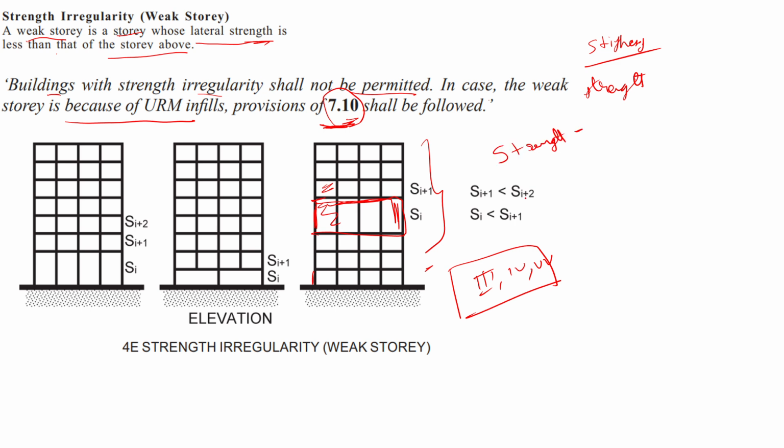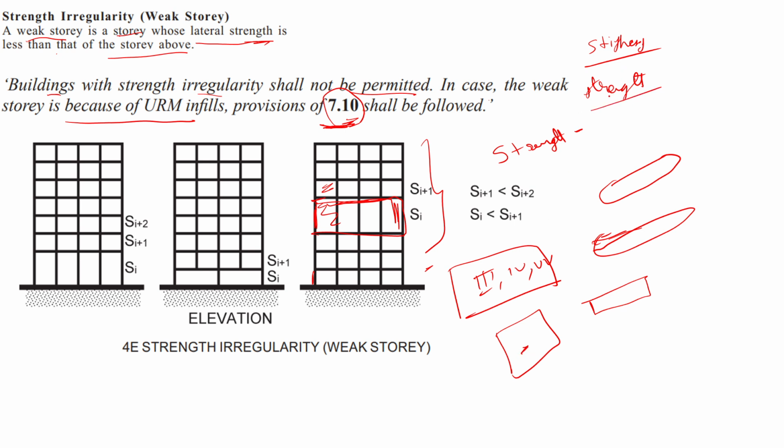It is just like if you take the example of a rubber band. What happens with a rubber band? It is a material which is strong. If you pull, it will take it. It has the strength to take it, but it is not stiff. It is not in a fixed shape. When you pull it, it comes back. But imagine a glass: it is stiff but it is not strong. So that is the difference between strength and stiffness, remember that.